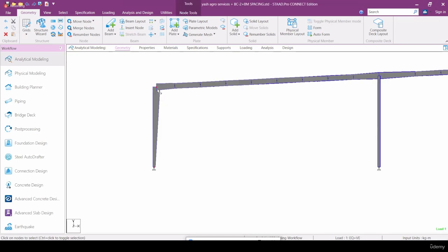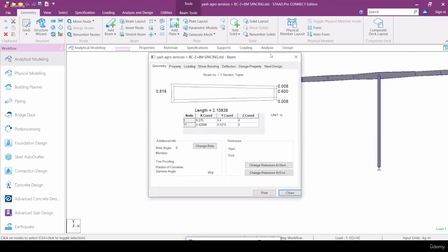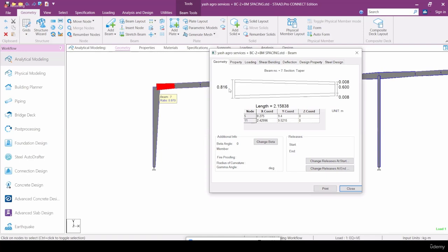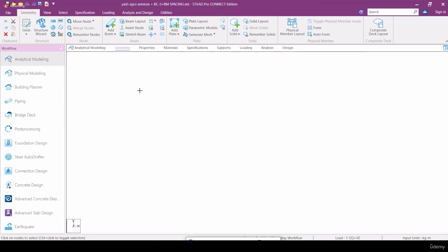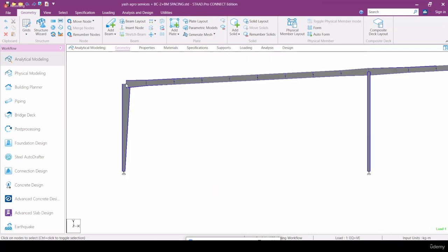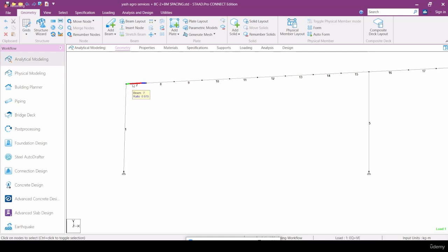No, my question is not that, sir. If you see the rafter, please click on that so that I can see the dimension. Okay. This dimension is 816 at the center of the column. Yes. But when we give the vertical splice in AutoCAD, this 816 should be at the flange of the column, right? Yes, exactly. No problem in that. Generally, this is the one we are designing, but yes, you can give offset here. I'll tell you how to give offset.